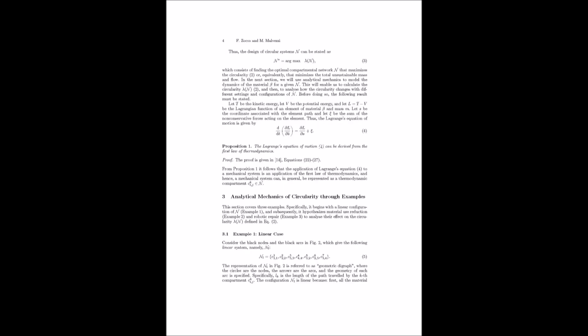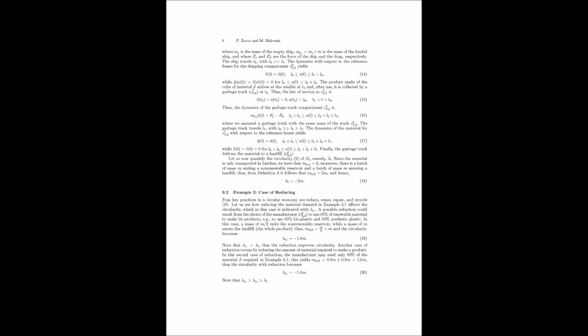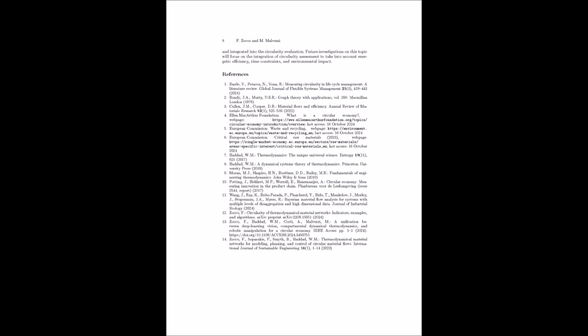This is where we finally calculate the circularity goal for this very linear system. Show me the numbers. Well, in this case, everything is moved in batches, so the ΔT part of the equation is 0. We're only dealing with MUB. We have 1 unit of mass, or M, leaving the mine, and 1 unit of mass entering the landfill. That gives us a MUB of 2M. So our circularity is -2M, meaning 2 units of mass are essentially lost in this whole process. It's kind of eye-opening to see how even this basic example shows just how inefficient a linear model is.